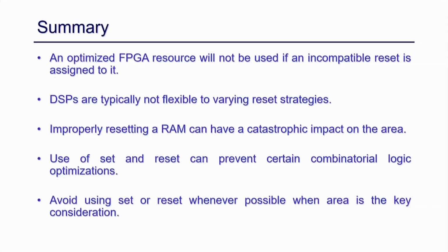Right. Specifically, we have discussed the shift register. You should not use reset for a shift register. You should not use asynchronous reset or synchronous set for DSPs, or as a whole you should not use reset for RAM. Specifically, you should not use asynchronous reset for RAM, because those have a very catastrophic effect on area and performance. Also, for flip flops you should usually keep the reset and set pin open, so that the synthesis tool can map certain logic as a reset or set, which has a better area benefit. Okay.